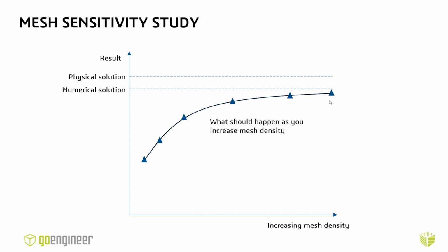When you do this for a lot of different types of studies, or for the heat exchanger, for example, if I just focused on making the cells smaller in the heat exchanger, I would likely notice that after about 2-3 cells between each fin, I'm not seeing much change in the pressure drops and the velocity gradients. It's fairly uniform, or fairly converged, at that point. So that's where 2 to 3 cells is coming from. It's this idea of a mesh sensitivity study.